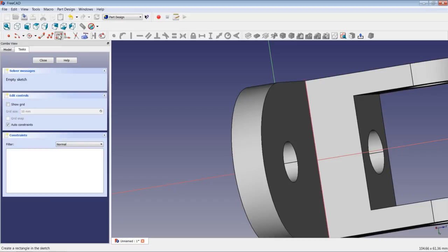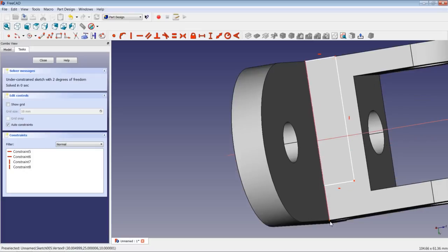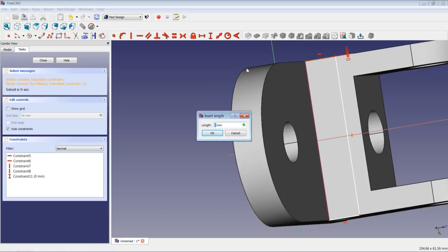for reference. So I can now choose to create a rectangle, and I can highlight this point here and give it a constraint that these 2 points are coincident, and I will also make this point here coincident with this point. I will then apply a vertical dimension to, no, I was wrong.